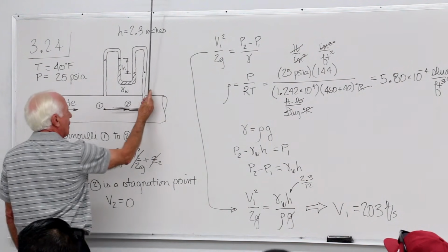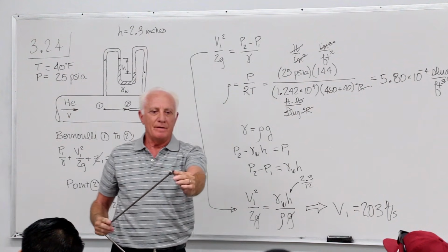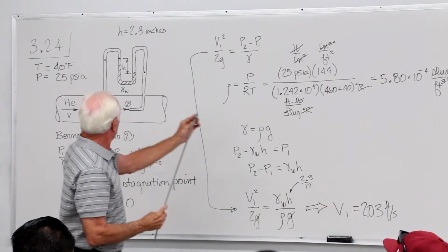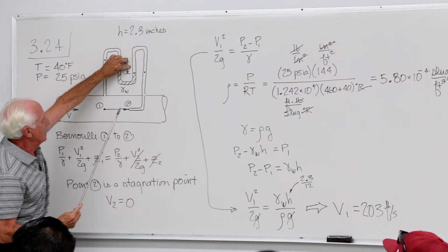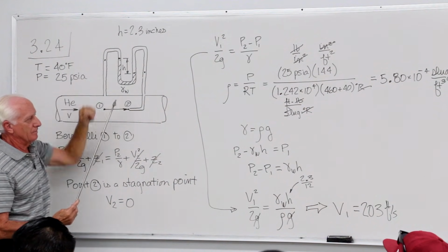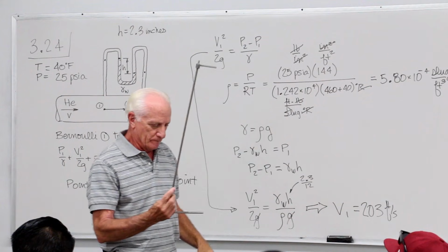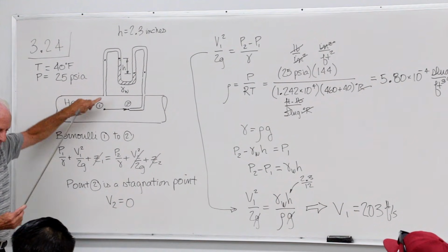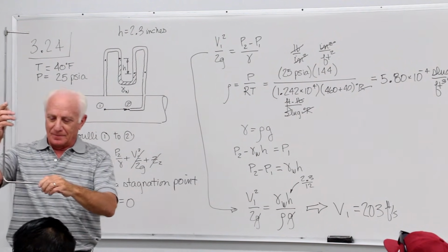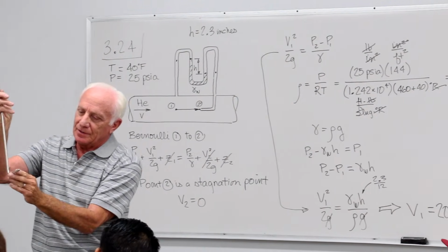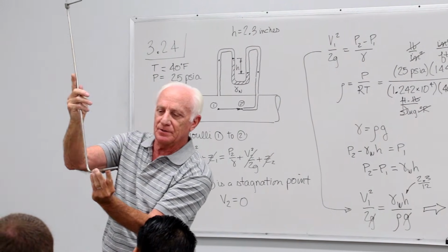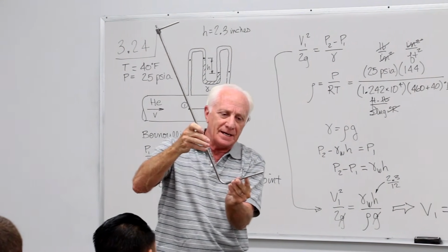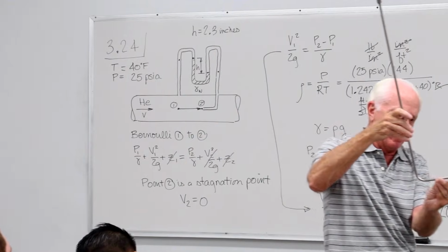There it is mounted in there. This pressure tap up here measures the stagnation pressure. This side, a part of this side, that tap measures that. Now, there are also static pressure taps. They're hard to see, but they're around the circumference right here at my fingertip. There are little tiny holes drilled in there, about 8 of them around the tube.